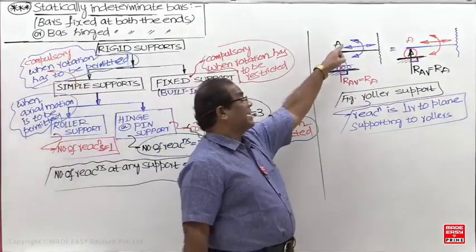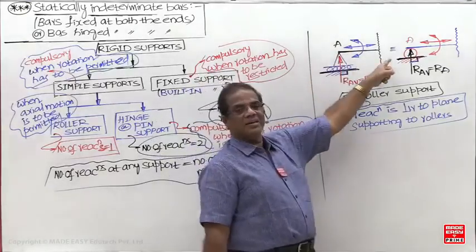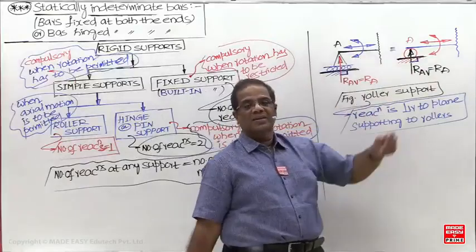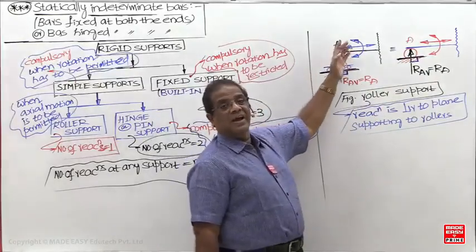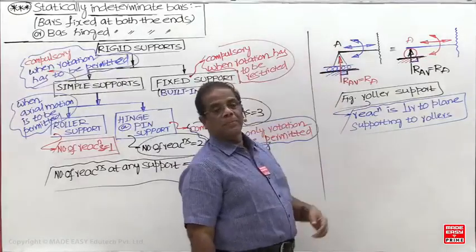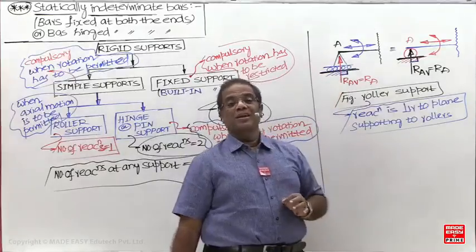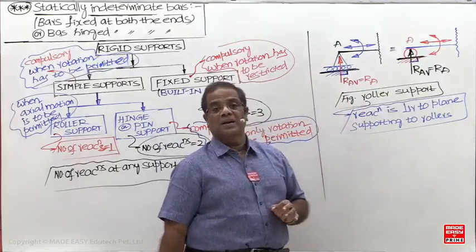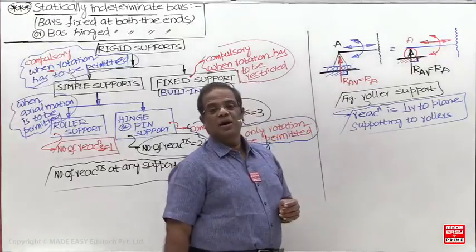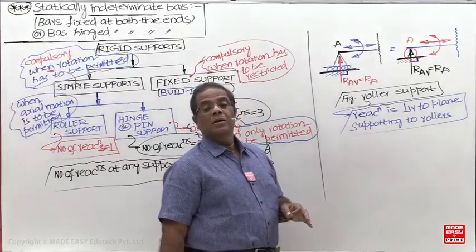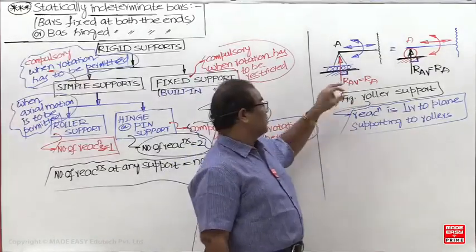Now at A, how many loads are possible? This black color line is a horizontal line, the longitudinal of the beam, the longitudinal of the member. A is at the extreme left side. At every cross section, how many loads have you studied? Axial load, shear force, bending moment and twisting moment. Here, only a vertical reaction is there. So axial load is 0, bending moment is 0, twisting moment is 0. Only shear force is there, from the vertical reaction.